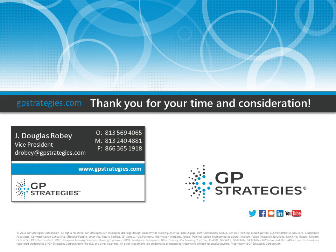So two things were done. One, a program was put into place on the critical equipment for installation to make sure that equipment was installed and aligned correctly. And the final part is all maintenance personnel went through a coupling, shaft alignment, and bearing installation course. The result of that was a decrease the first year of $3 million of savings in bearings. So just that one quick impact, based on what they found from a critical piece of equipment, resulted in a net savings of $3 million. So these are little things, defects, that if you track properly can be fixed very simply, either with critical procedures or documentation being corrected and then a training program followed by that.